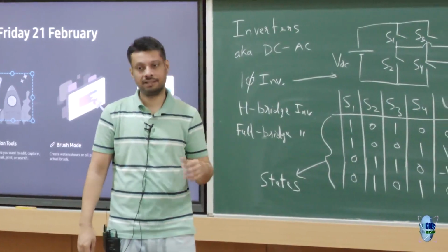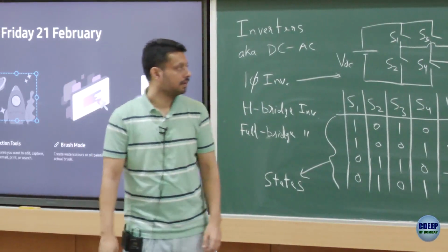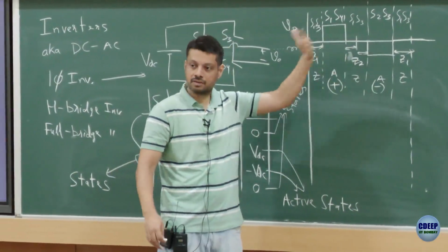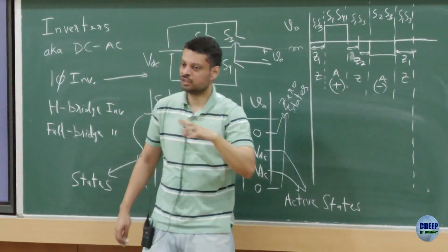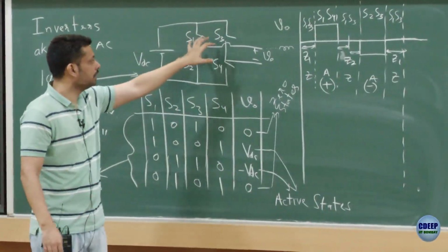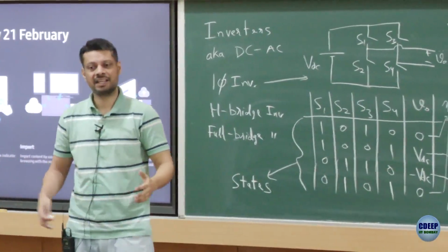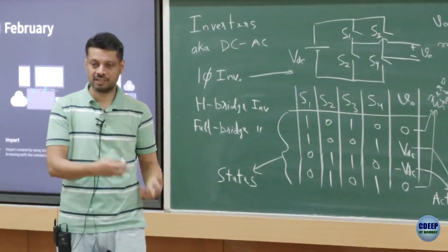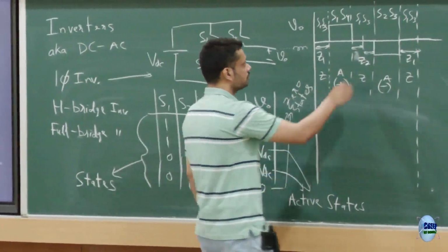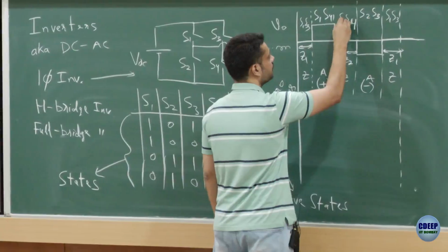S2, S3, S4, same. If you don't use this sequence and replace this one with S2, S4, it is still the same. So the switching losses will remain the same. The only thing is that now your stress is not only on the two switches in terms of the RMS current. So the conduction loss is in a way getting divided also, because finally you have to cool these devices down, and so on. So a lot of those challenges. So, we can use S2, S4.